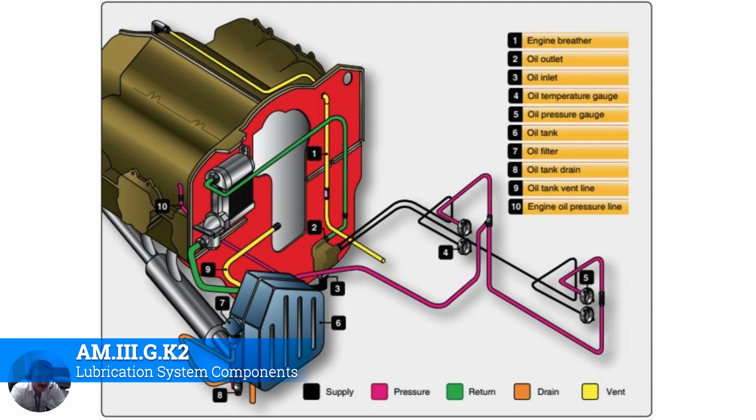So you have this gray apparatus up here in the top left. You can see that's the whole crankcase, where the engine oil is going to go. Then the tank is going to be on the outside. Now, this is not necessarily the case on all aircraft. Like on an IO-320, the oil tank is just basically on the bottom. It all comes down to the bottom. Some engines will have a remote engine oil system that will pipe into it from somewhere else on the aircraft. Usually it's still pretty close by, but just know that you can have two different kinds of configurations. We're going to get to what they're called here in just a minute.